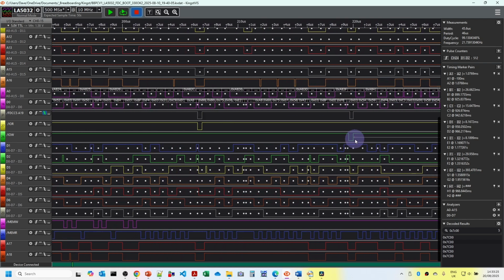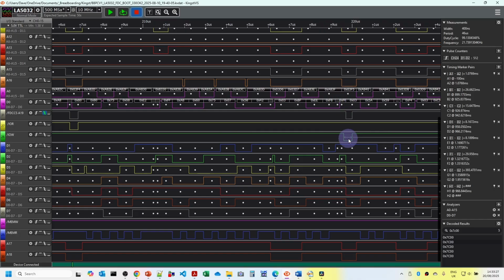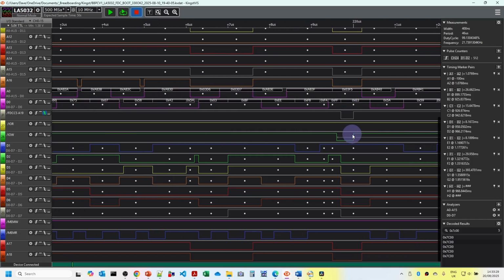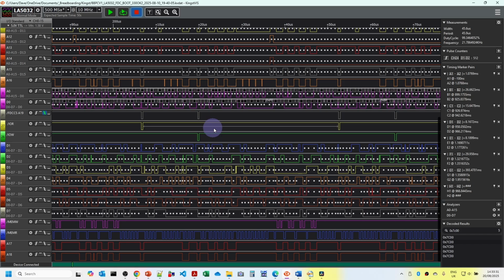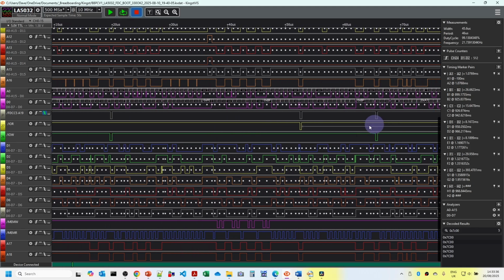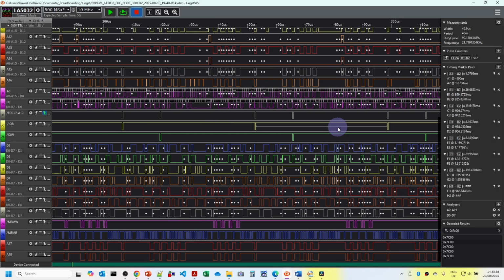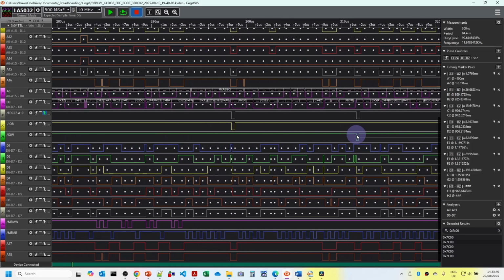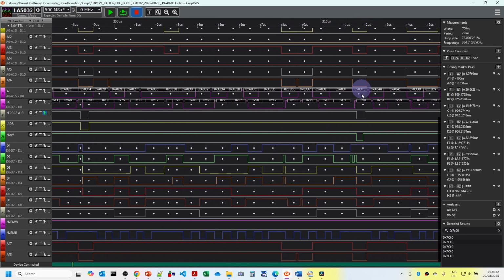So the first thing that we have to do is send a specify command. The specify command is 03, and then there's a couple of bytes we have to send after it, related to various timing parameters of the floppy disk drive, things like head settle times. In particular, this byte here has the non-DMA bit set. Normally on most PCs this would be 02, but because we're disabling DMA for our programmed I/O here, this bit has been set.